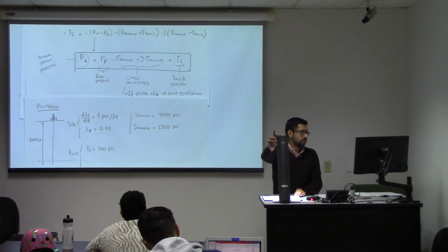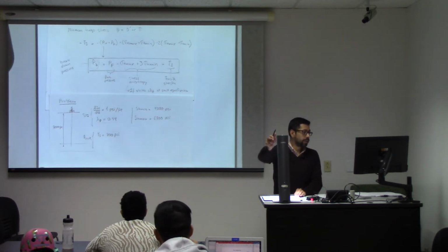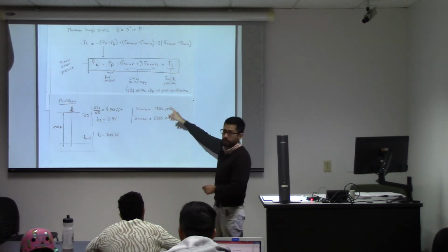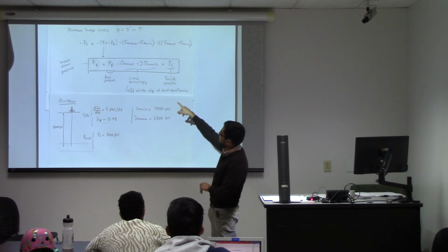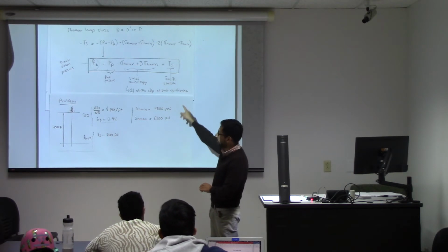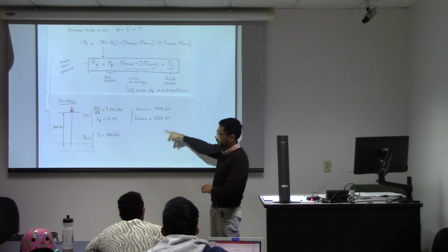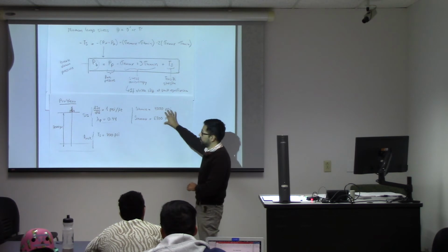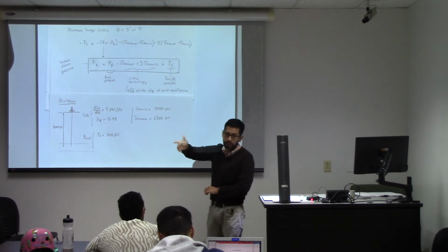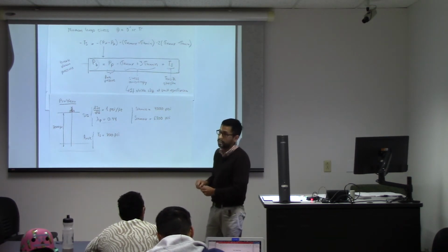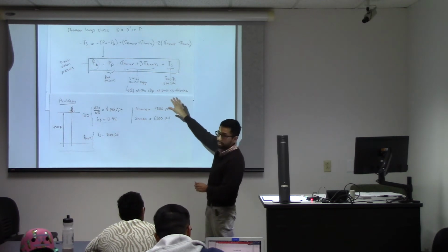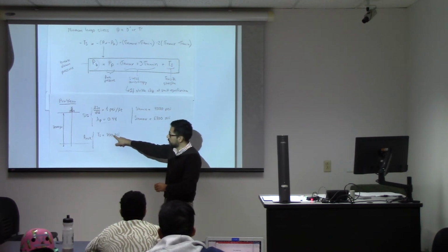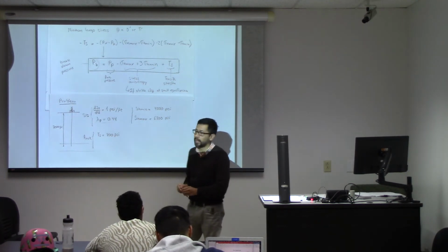So you know everything about this. You know how to solve this problem, because look at the equation. You need sigma h max, you need sigma h min, effective stresses. You know how to do that. You know pore pressure, you know total stresses. You know how to do that. Here I'm giving you those values. In some other problem, I might not give you those values. You have to calculate them on your own. But I'm giving you those values now. And also you have run Brazilian tests that allow you to compute what is the tensile strength of the rock.